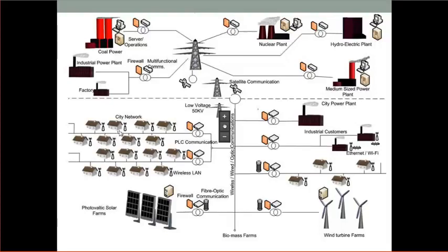Well, the other thing is in your residential customers, I talked about going and reading the meter once a month. So, you read the meter and you know how much power they used over the course of the month, and you send them the electric bill every month. But what you'd really like to be able to do is to make the power in the evenings and late at night, when your load is lower, maybe cheaper, or charge the same rate, but in the afternoons, that afternoon power, maybe you want to make that a little more expensive so that you're giving them an incentive to be more judicious in their power use.